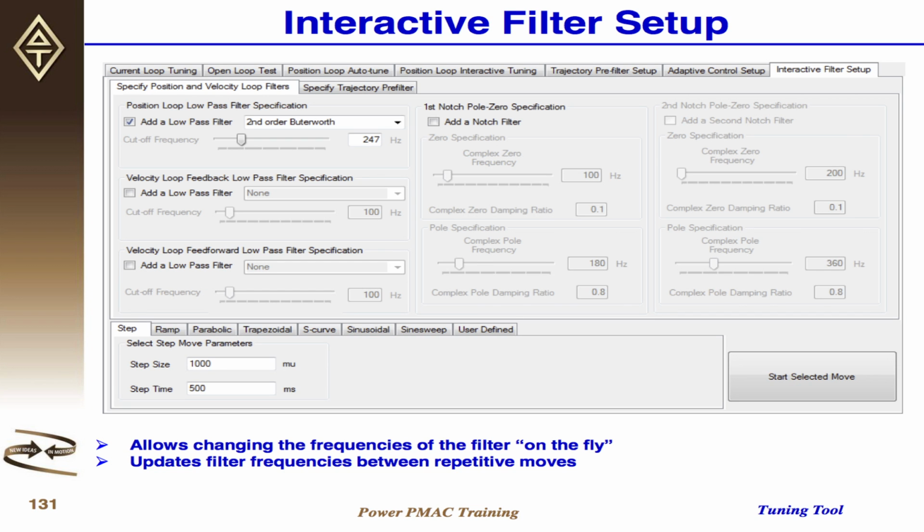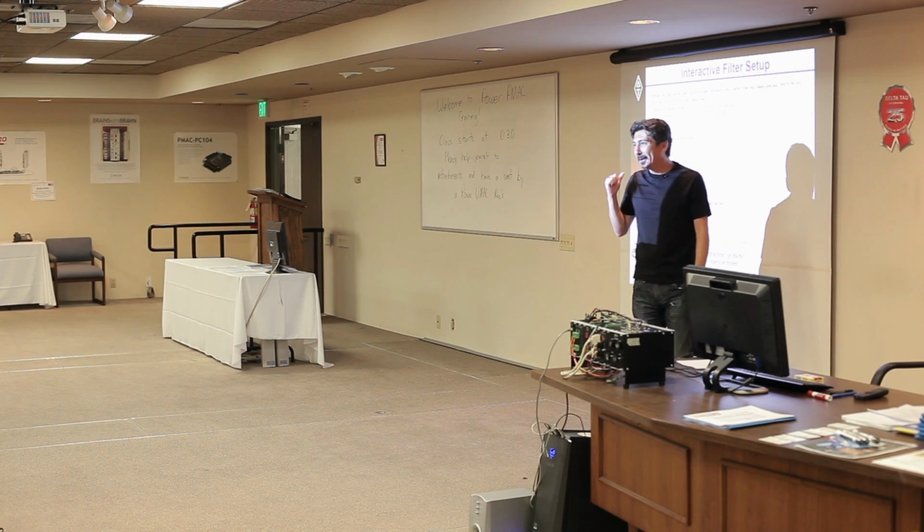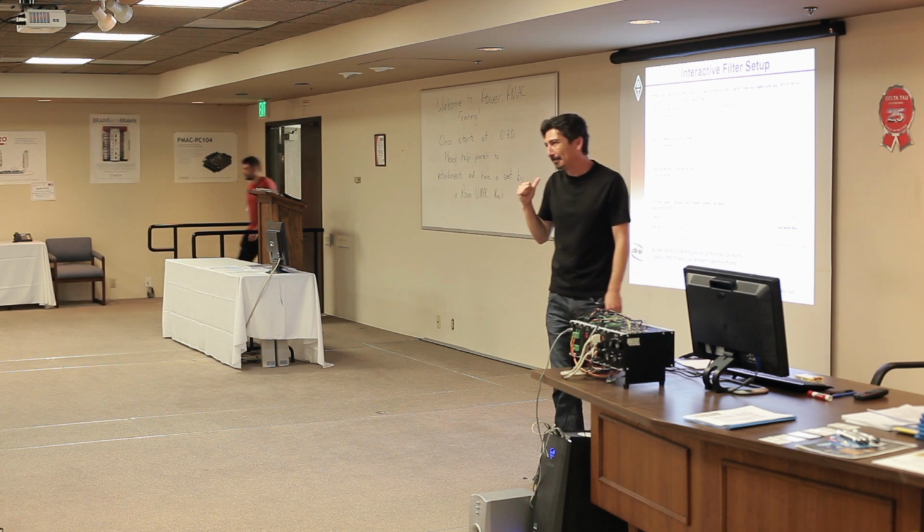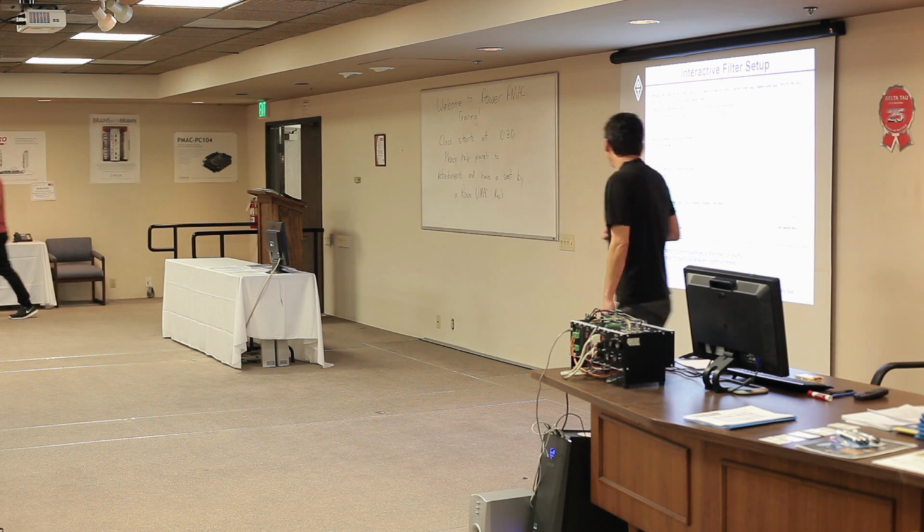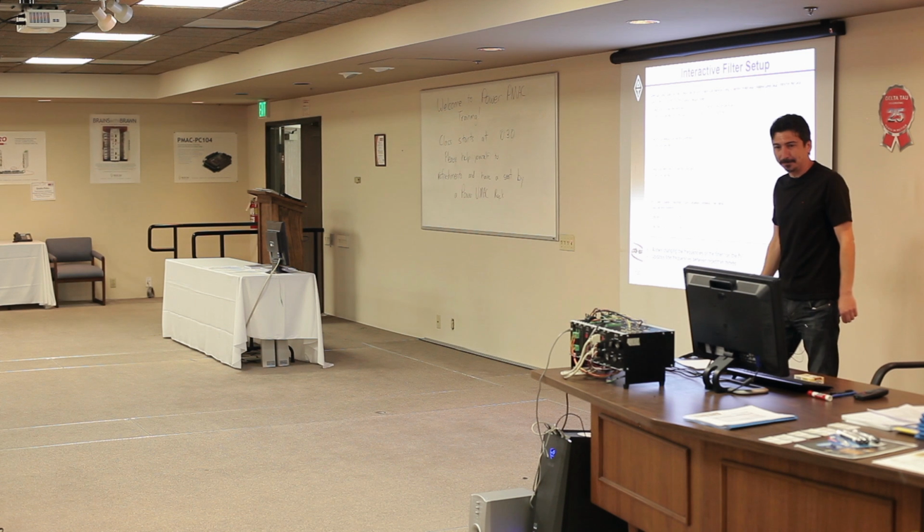So that was the idea behind it. Of course, you have to be careful. That's why we make sure that this is for advanced users. If you set this dial too low, for example, for the low pass, you can make the system unstable. But that's the main idea behind it.